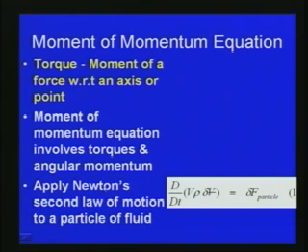So, let us consider a control volume which we considered earlier. If we consider the total derivative d/dt of (v rho del v), where del v is the corresponding volume, that should be equal to the effective force on that particle. With respect to Newton's second law we can write the rate of change of momentum, d/dt of (rho v del v), equal to the net force on that particle. That gives equation number 1.